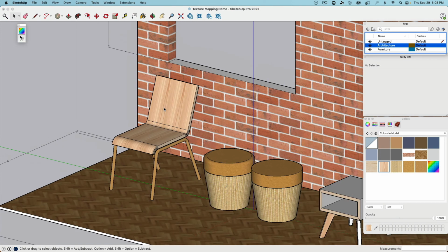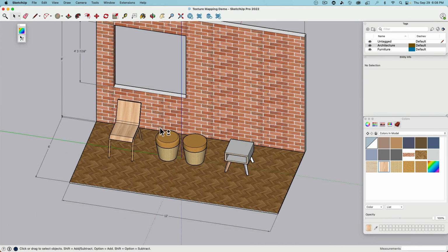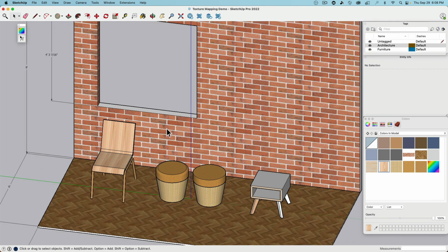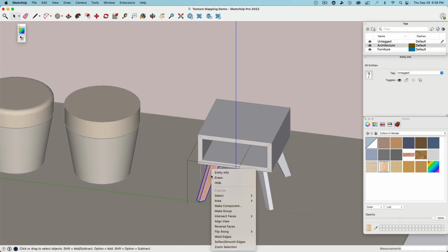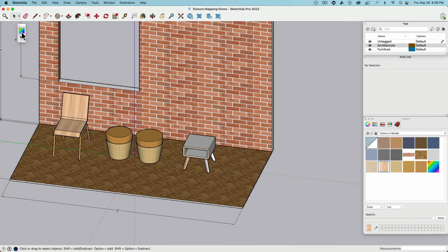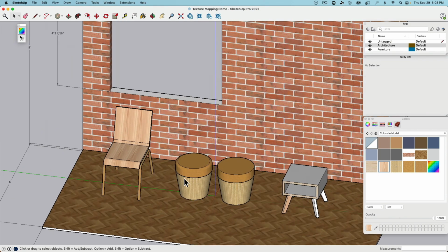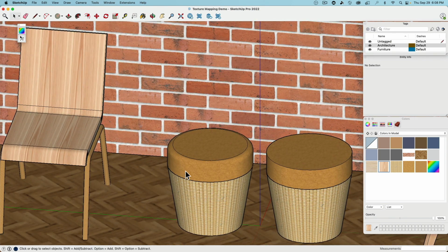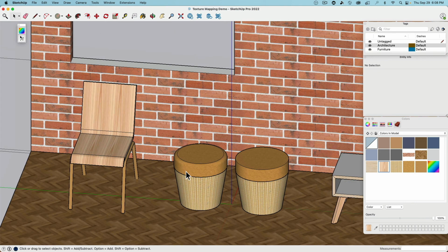Very good. Okay, so that was pretty much the crash course into how to UV unwrap in SketchUp with the built-in planar mapping tool. When we use the texture and position command, and also the free sketch UV, which then, as you can see, allows us to texture really complicated patterns.